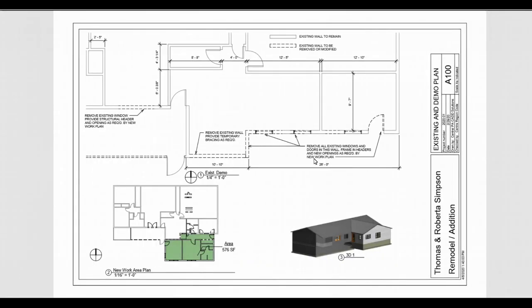So really, whenever you're doing this, I'm not just going to do the demolition without looking at the new work plans. I'm going to basically use those two drawings together to look at these different things and see what's going on as a project as a whole. A lot of times I might remove windows or doors and fill that in. A lot of times the door might just be replaced or something, so it's really important to pay close attention to the notes and see what they say as well.